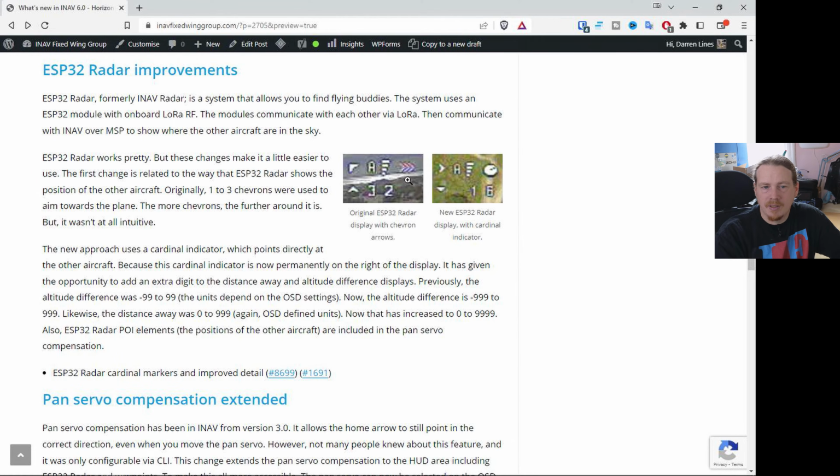Originally on our head-up display, this is the sort of layout that we would see for the other aircraft. We would have letters A through to D for up to 4 craft. You can see we have the RSSI, and we have a relative heading. If you don't know relative heading, the tops of my fingers are the fronts of the planes.